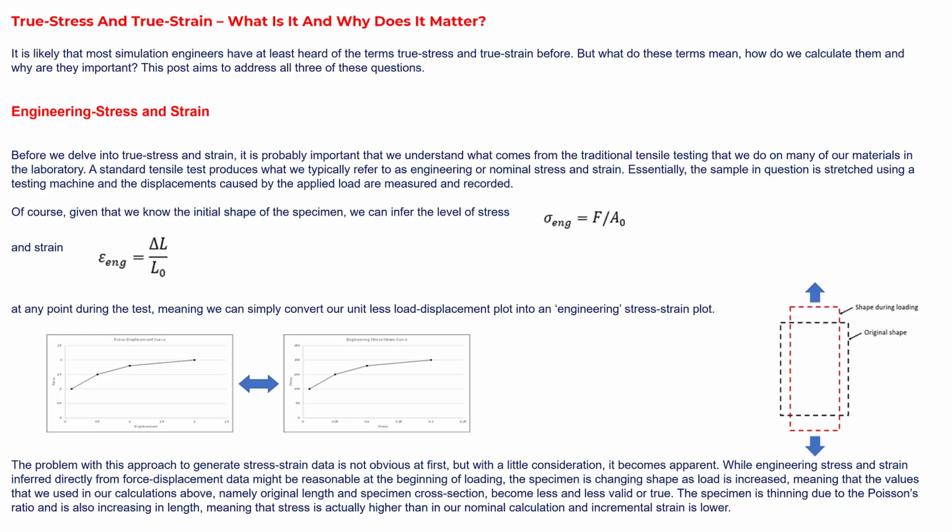If you're a mechanical engineer or an aeronautical engineer, you have gone through the universal testing machine, right? Where we conducted tensile testing. A simple rod is taken, one end is fixed and it is stretched. We note down the displacement results along with the force applied, convert that into engineering stress, and find out the true stress strain values as well using these.